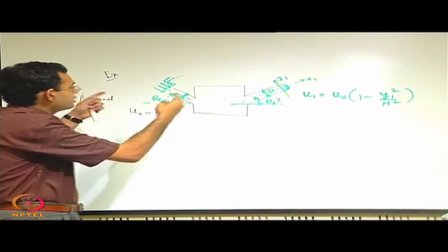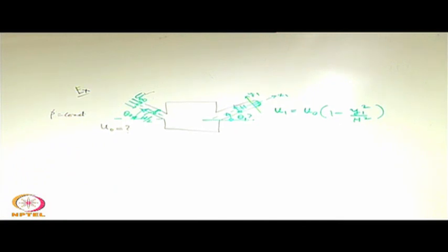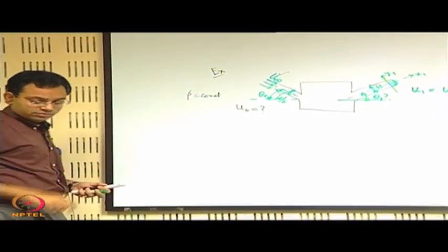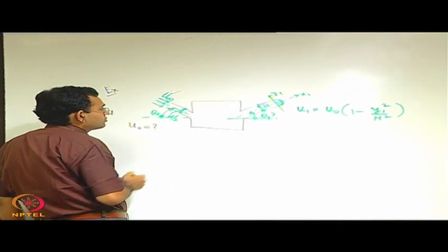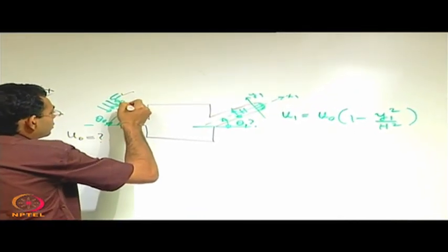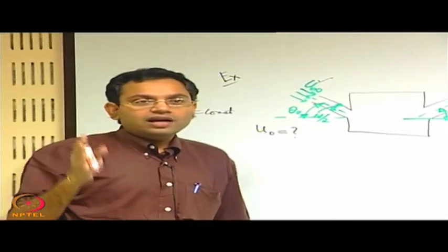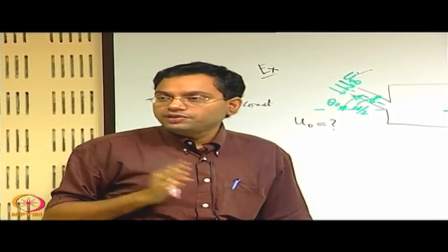Again it looks like a situation where mass conservation should be applied, and if you want to apply the integral form of the mass conservation, let us say that we consider a control volume. So, what should be a good choice of the control volume? A good choice of the control volume is something where across the surface we are totally confident about the velocity field.